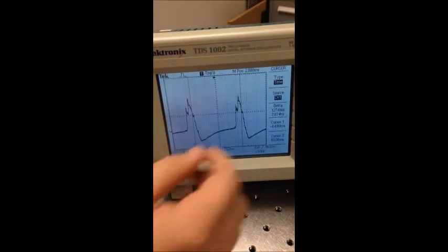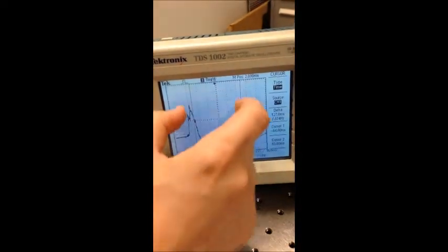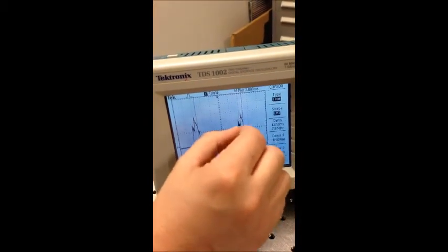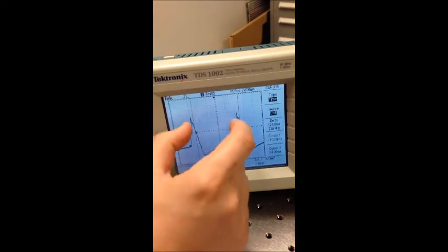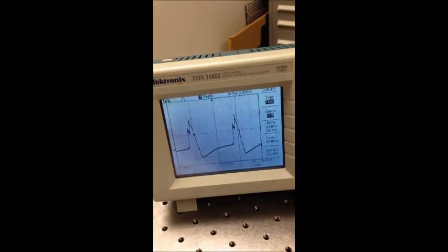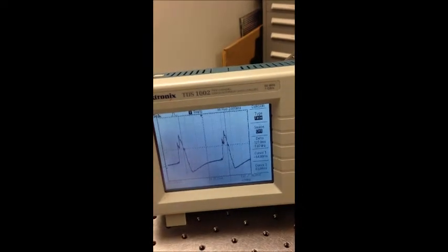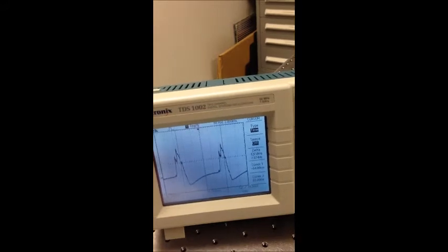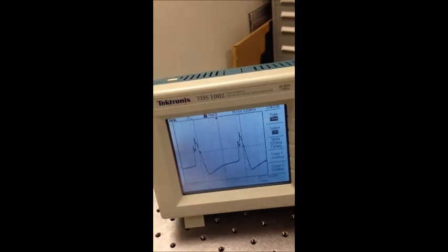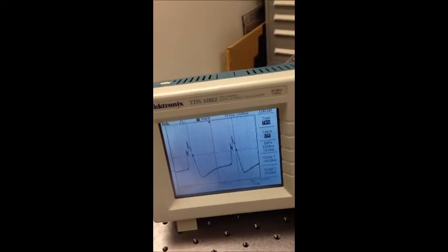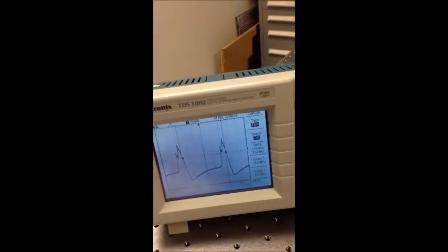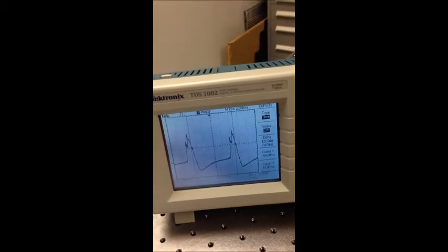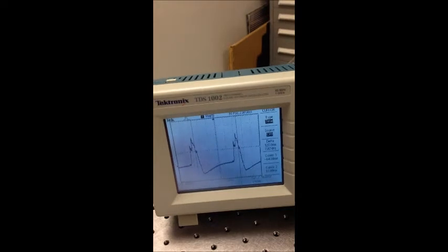On the RF, we measure the distance between those two peaks and also the distance between the larger two peaks. The distance here between these two peaks was only 7 milliseconds, but between the larger peaks was 127 milliseconds. With that, we're able to get that our frequency was 551 megahertz, which was very close to the stated frequency of 559. And also, we were able to find that the cavity for our laser was at 27.2 centimeters, and the casing is about 33, so 27.2 centimeters for the cavity makes sense.